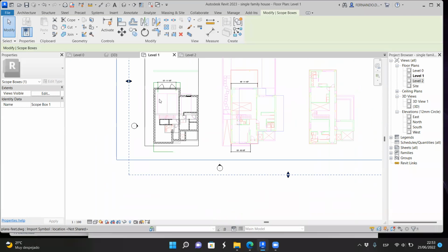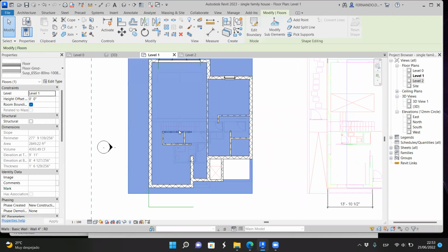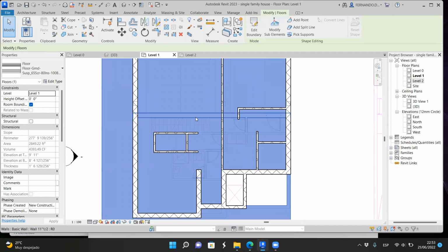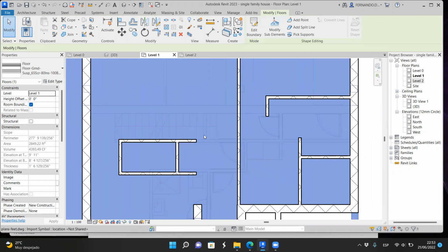And here on level 1, the first thing we have to do is open space, because if we go up, we don't need to have a floor here, because we don't want to hit our head on the slab, on the floor slab. So the first thing we have to do is to open a void, as we did here. We have to open a void for that staircase. So apparently, you see that we have, well, it's difficult to tell, but I'm going to use this line here, and this is the end of the void.